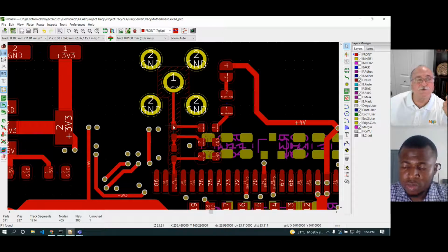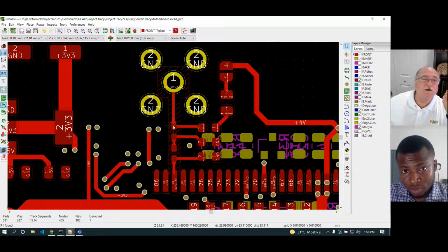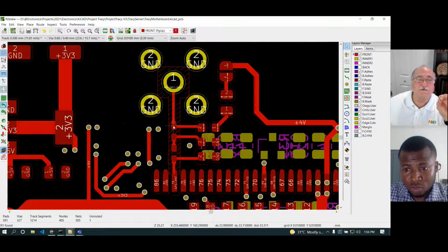If the distance between the driver and receiver, or the size of the discontinuity, is greater than a quarter wavelength, then the reflection will be 100% of the magnitude. And so you run the risk of having a second order reflection. A discontinuity this small would take an extremely high frequency, most likely not found on an FR4 printed circuit board, to make any difference in the movement of those fields.